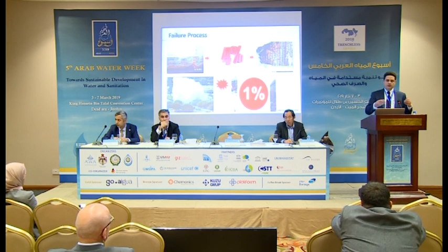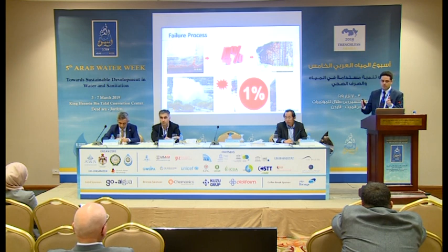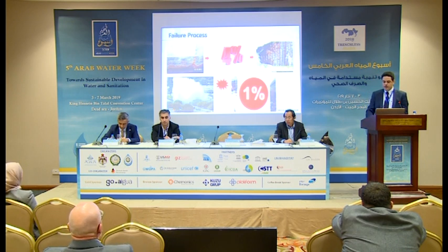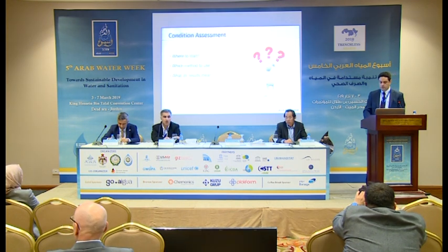So if you have pipeline that consists of thousands of pieces of pipe, in fact, by finding those that are distressed and rehabilitating them, could be a handful of pipe pieces in the pipeline system. So it is something to keep in mind, therefore not necessarily considering replacement as a first option.